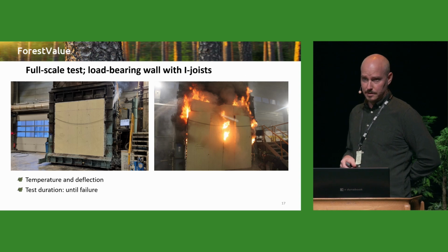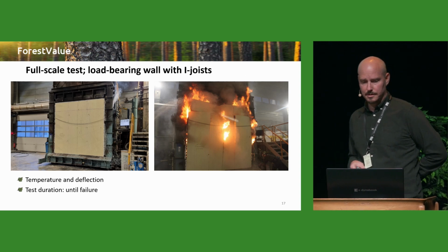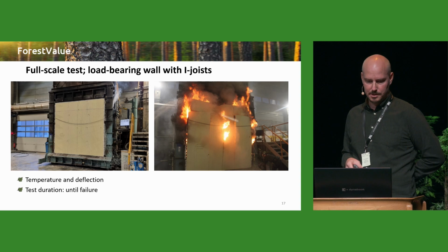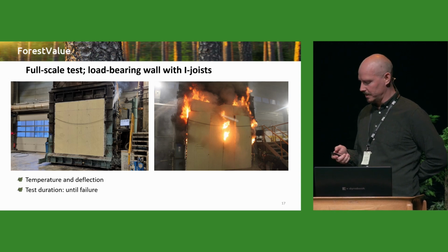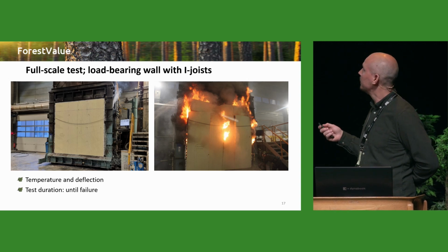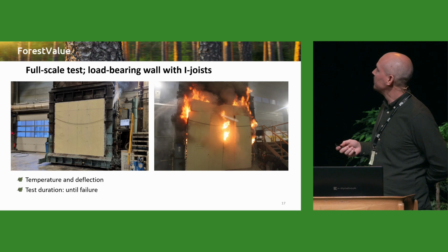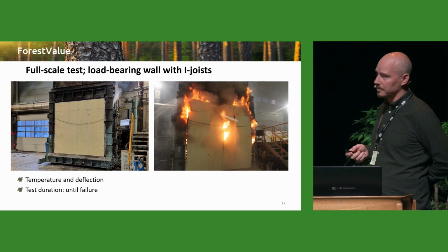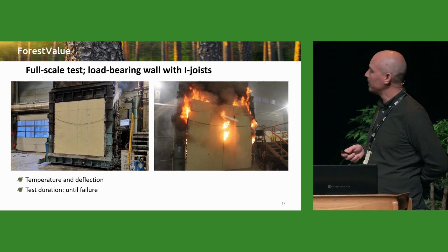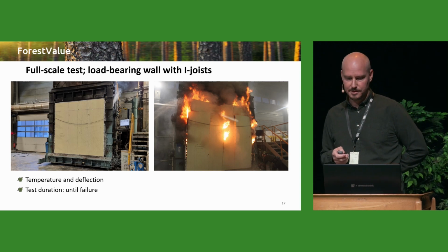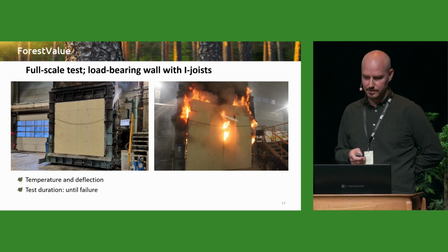Similar, we did a load-bearing wall test. It's same measurements, temperature and deflection, but we're having the loading up here, pressing down with hydraulics. And to the left, you see the test after roughly 30 minutes, and to the right, it's after failure, of course.